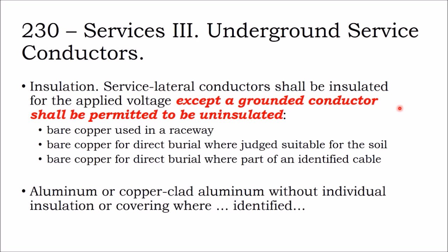In other jurisdictions, they say, no, PV cable is a 2000 volt cable, and USE cable is a 600 volt cable, and we want you to use the 2000 volt cable even though you're only at 600 volts because it's a more robust cable. That jacket is more robust. That's why it can withstand a higher voltage.